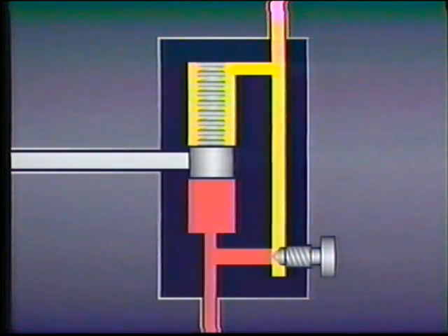In this type of valve, the compensator spool blocks flow out the tank port until pressure rises high enough to overcome the combined pressures of the spring and the pilot pressure downstream of the needle valve orifice.